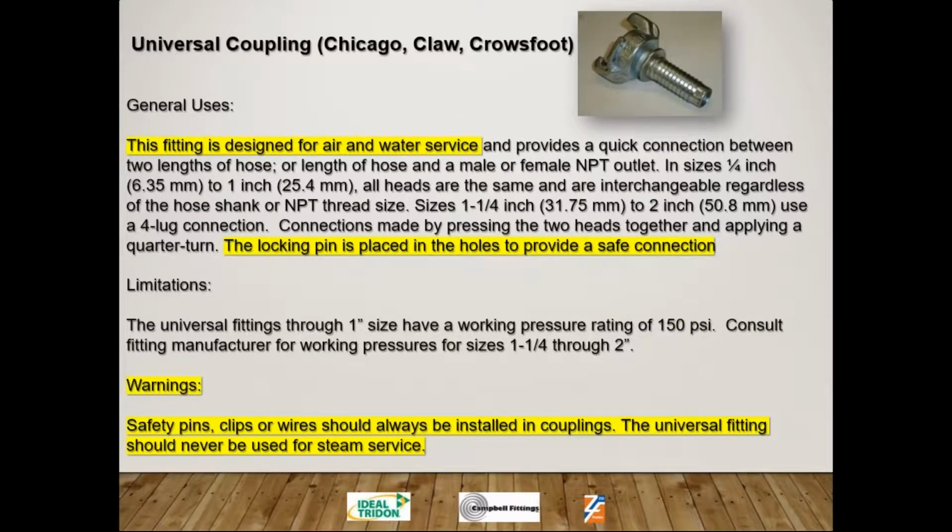So now jumping into universal couplings, Chicago fittings, crow's foot, pretty typical for air and water service. The big highlight there is a locking pin is placed in the holes to provide a safe connection. And the big warning is safety pins, clips, wires should always be installed in these couplings. And the universal fitting should never be used in steam service. So that's our first 2 fittings, cam and groove, and universal coupling, not to be used in steam service.